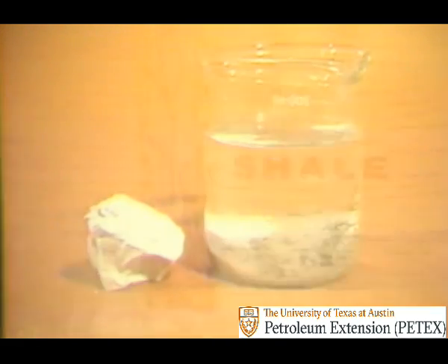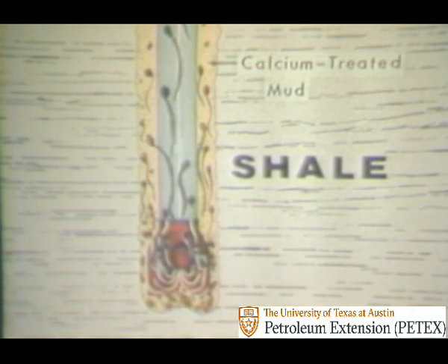Like when shale is being drilled, that contains various types of clays. It's not good for these drilled solids to hydrate because they have bad effects on borehole stability and mud properties. Calcium-treated muds keep the solids from hydrating too much.